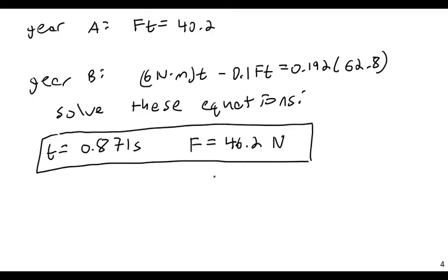Again, in summary, what did we do with this? Well, we constructed momentum and impulse diagrams. We looked at the initial angular momentum, we looked at the final angular momentum, and we included in our drawings any forces on there. Now if you are looking at a purely rotational system and you have some forces acting through the mass center, it's not particularly important to include those forces, but for the sake of completion you can. But in general, we're going to be looking at all of the forces there. So again, we set up the diagram of initial angular momentum, final angular momentum, and any impulses on there, and then work through our algebra from there.